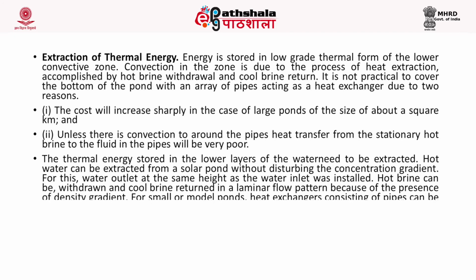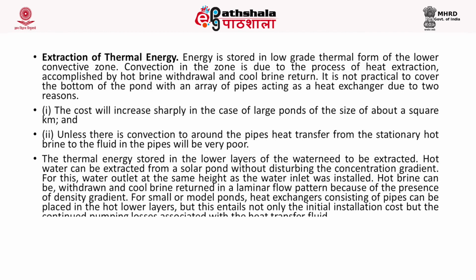Once the collection of the solar energy occurs in this pond, it is stored there and has to be extracted. So the energy stored in the low-grade thermal form of the lower convective zone has to be extracted. The convection in the zone is due to the process of heat extraction, which is accomplished by hot brine withdrawal and cool brine return. So it is not practical to cover the bottom of the pond with an array of pipes